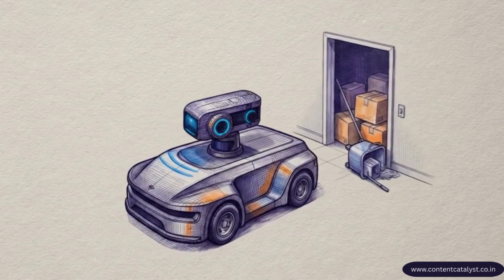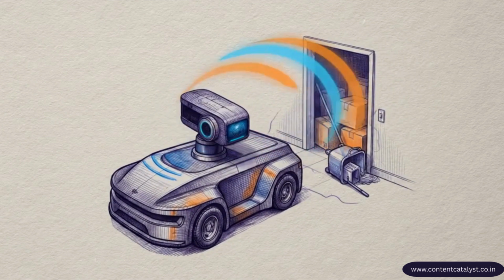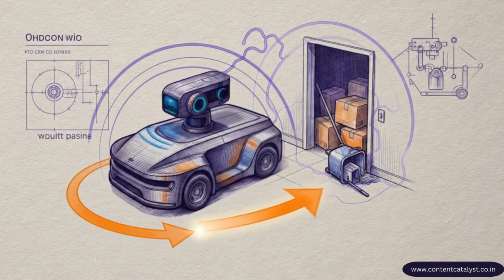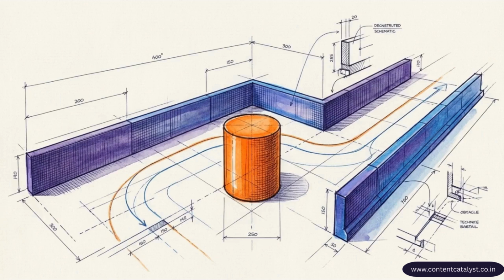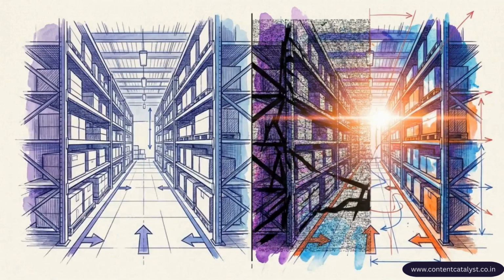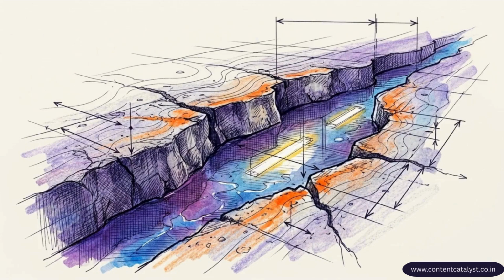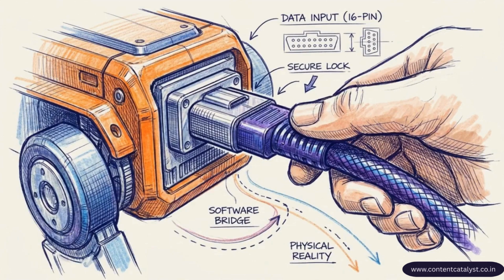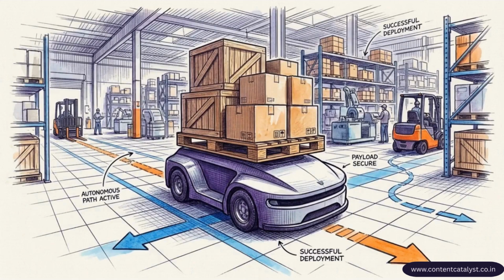You must relentlessly test recovery behaviors. Watch how the logic handles failure states when navigating through a restricted physical choke point, like a cluttered doorway. Build a standard known baseline test world and run it immediately after every major code change to ensure you haven't broken your core navigation. Successful sim-to-real transfer relies on building robustness against noise, ensuring your code functions across the unpredictable variables of the physical world. Standardizing your workflow around a pragmatic, reliable simulator like Webots allows your engineers to confidently bridge the gap between their initial code and a safe, physical, autonomous machine.